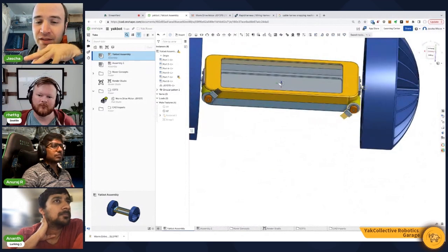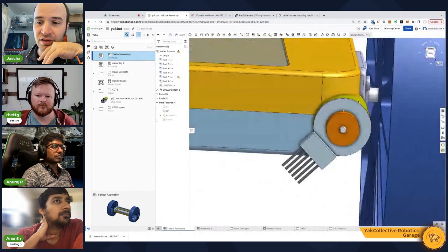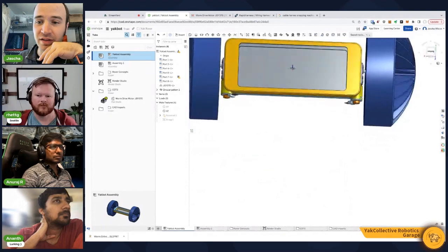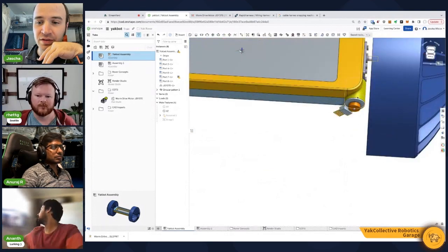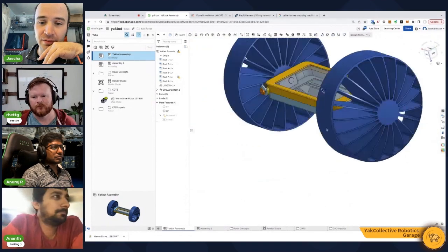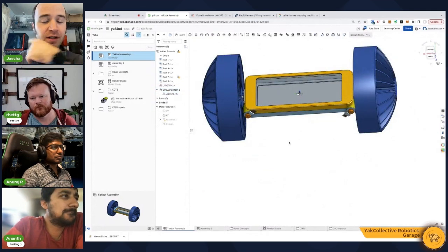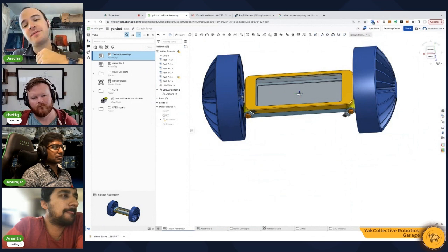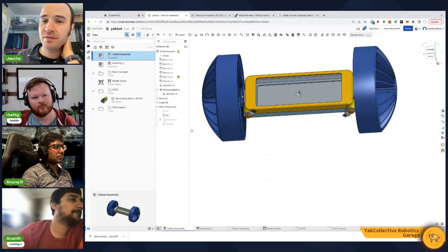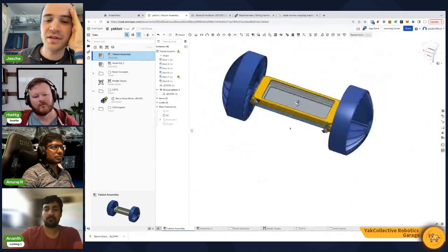So this is my kind of hack to do a mirror: I used a circular pattern rotated around this mate connector, which produces my desired result, which is to have two motors that are mounted into the frame on either side, but in the correct position. So these are fully defined. They are exactly in the position that I want them in, and then we can move forward. But that's just another Onshape gotcha. In SolidWorks I would have used assembly mirror, and it would have asked me to disambiguate which orientation of the part I wanted the part in, which is buggy and weird in its own way.